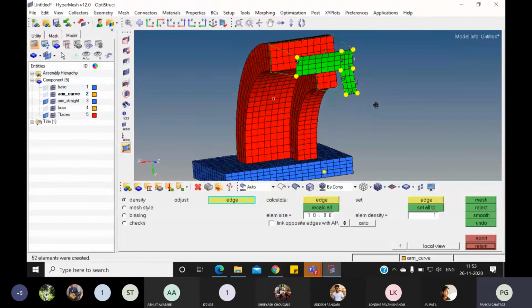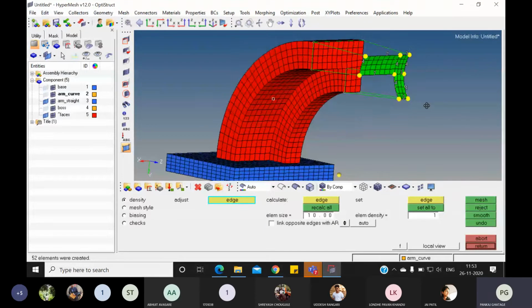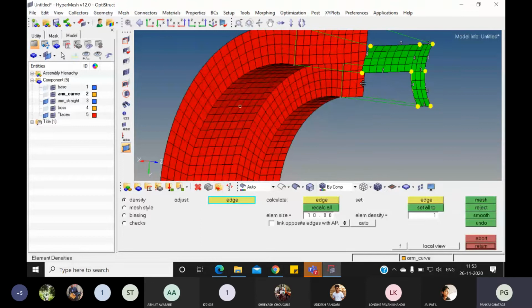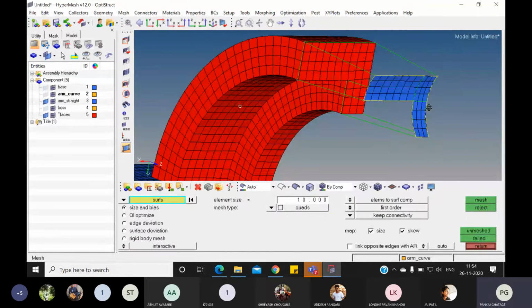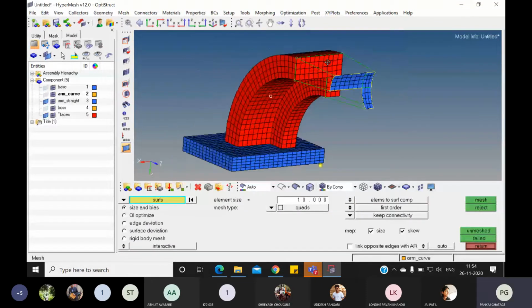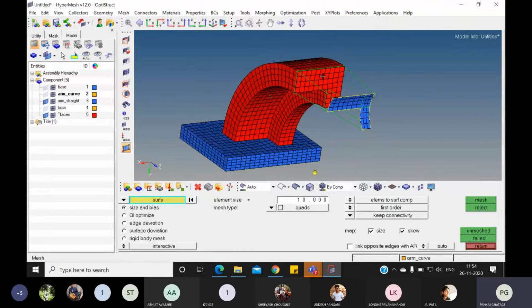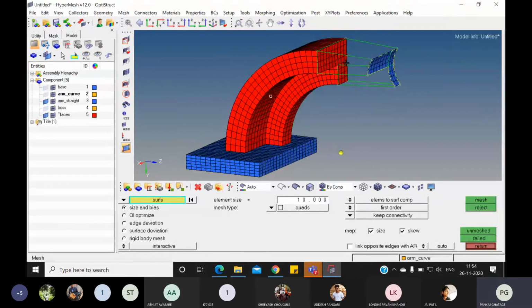So look at here whether it is correct or not. Now pattern means the same element pattern should be there. Density 1, 2, 3, 4, 1, 2, 3, 4, and then this one 1, 2, 3, 4, 1, 2, 3, 4. So along these 8 elements are there. This 8, this middle one 3, and this one is 4. So same pattern I have generated here. So I will go to this other part now. Same elements will be dragged along the taper direction.